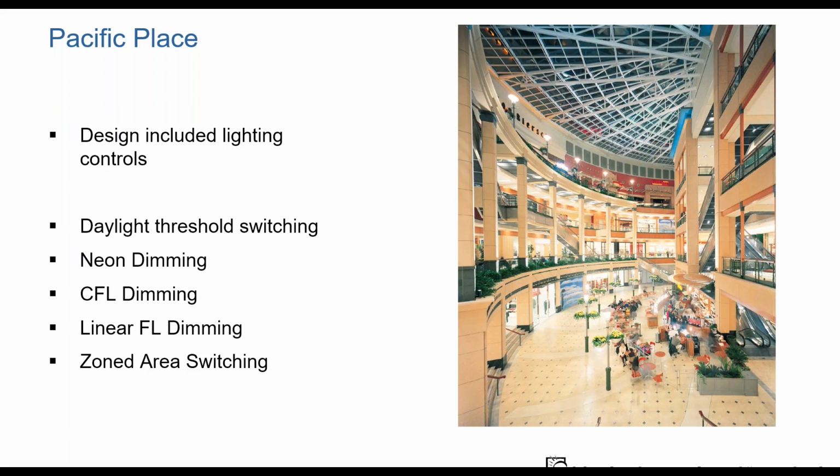A key part of this, to bring this in with respect to controls, is that we had spent a lot of time developing the lighting controls. Those of you who know me will know that this is a particular passion of mine. I like to be able to refine the lighting, and I also like to make sure that the lighting responds to things like daylight and external stimulus. So we had daylight threshold switching, we had neon dimming, compact fluorescent and linear fluorescent dimming, and we had pretty closely defined zoned area switching in this space.